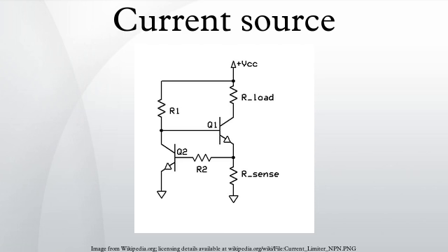The diode drop tracks the VBE changes due to temperature and thus significantly counteracts temperature dependence of the CCS. Resistance R2 is now calculated as given, since VD equals VBE equals 0.65 V. In practice VD is never exactly equal to VBE and hence it only suppresses the change in VBE rather than nulling it out. R1 is calculated as given. This method is most effective for Zener diodes rated at 5.6 V or more. For breakdown diodes of less than 5.6 V, the compensating diode is usually not required because the breakdown mechanism is not as temperature dependent as it is in breakdown diodes above this voltage.